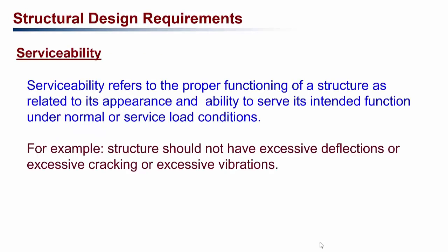The structure has to be serviceable. By serviceability, we mean during the day-to-day life of the structure should be functional and it has to satisfy all the functional requirements it is designed for. By functionality, it also means that it shouldn't cause any discomfort to the occupants or the users of the buildings as well. For example, the structure, if we are designing, should not have any excessive deflections or vibrations, or if it is reinforced concrete, it shouldn't have any excessive cracks as well.